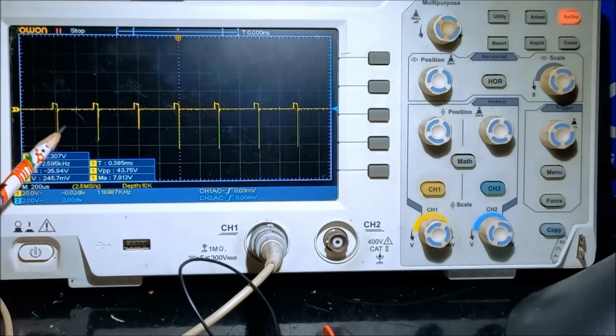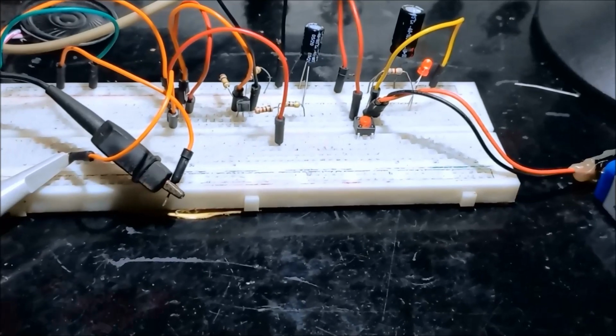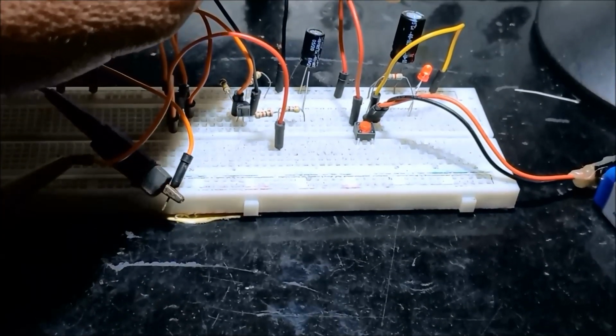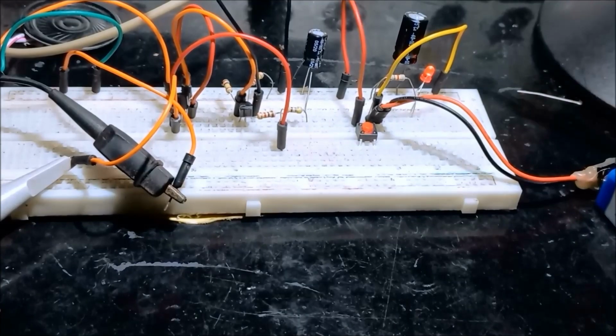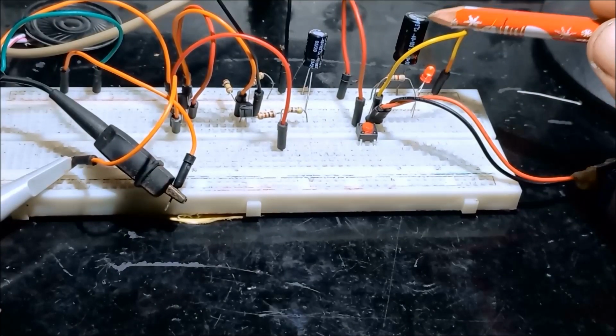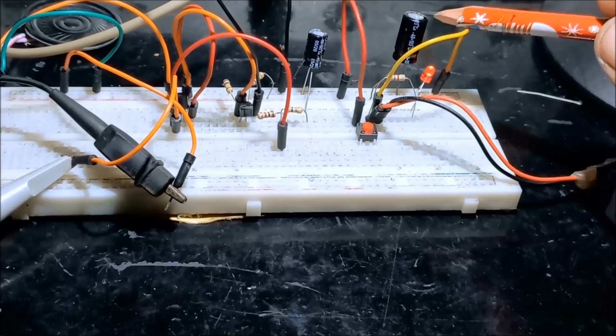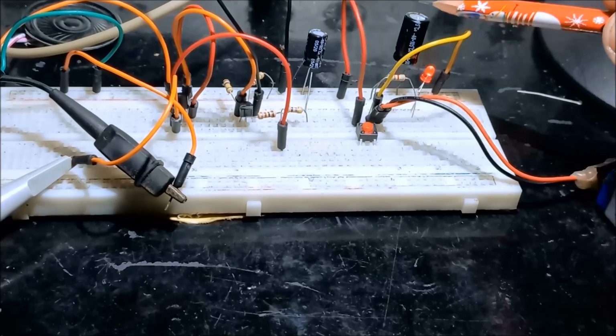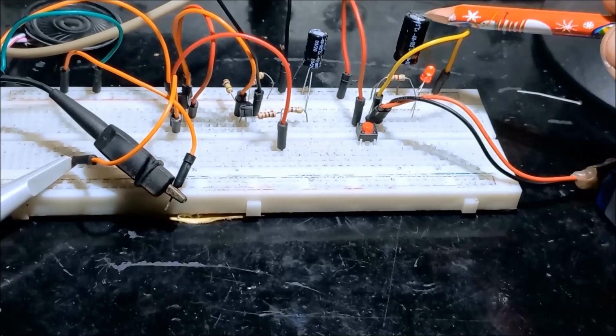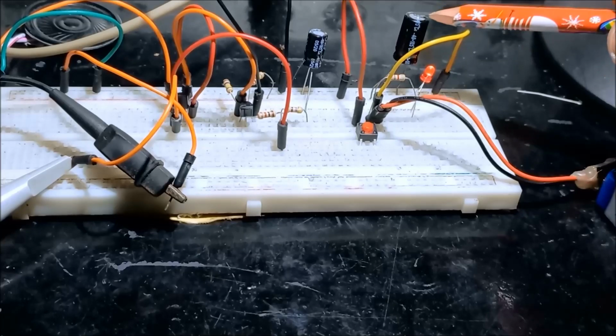So that is the effect of charging and discharging of capacitor. And you can hear the sound as long as there is power. In our circuit, we have this bulky capacitor. That is the one supplying the voltage now to the whole circuit. Once there is no charge for this 1000 microfarad capacitor, the sound stops. You cannot hear the sound because there is no charge inside this capacitor.